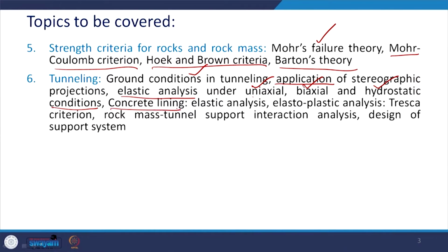Then elastic analysis of the tunnels under uniaxial, biaxial and hydrostatic conditions, and when we excavate, tunnels are to be provided with lining. So, here in the scope of this course, we will discuss the concrete lining, and we will study elastic analysis as well as the elastoplastic analysis, and for elastoplastic analysis, we will take up the Tresca criterion.